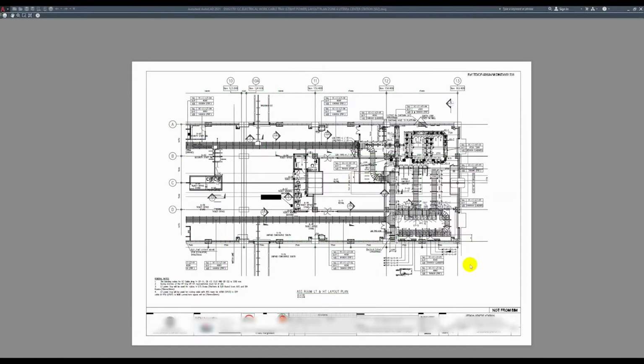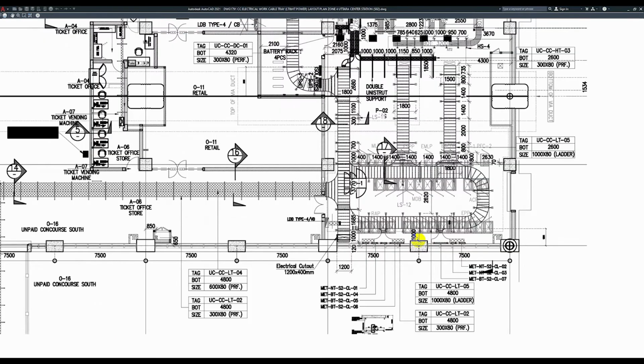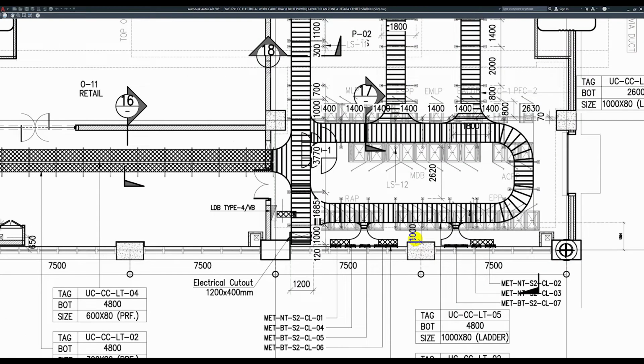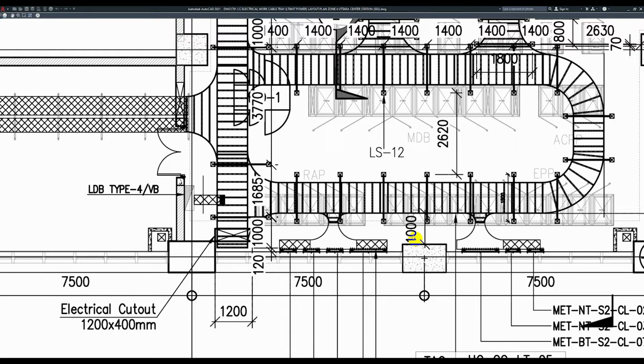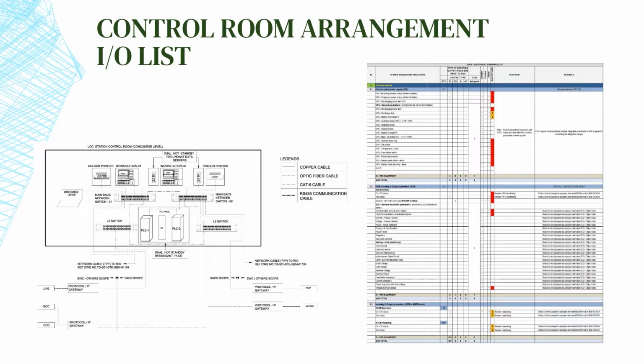I prefer to solve the cable tray route in drawing so that people at site can do the installation without any hitch. I had to prepare hundreds of fabrication drawings for Unistrut and all of its fittings to fabricate it in local workshop. For any automation project, from a small building management system to distributed control system, I would prefer to start with preparing the IO list and then go to the other parameters.